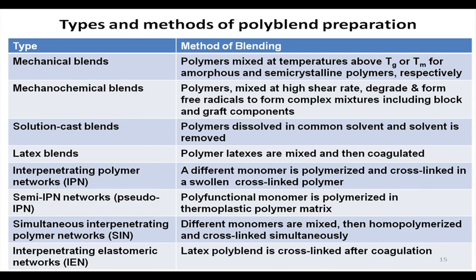In those cases, after proper selection of the solvent, the component polymers are dissolved in a common solvent, and they are mixed, and after mixing the solvent is removed by evaporation, and that can be recovered for reuse, and the product becomes a blend of two component polymers.